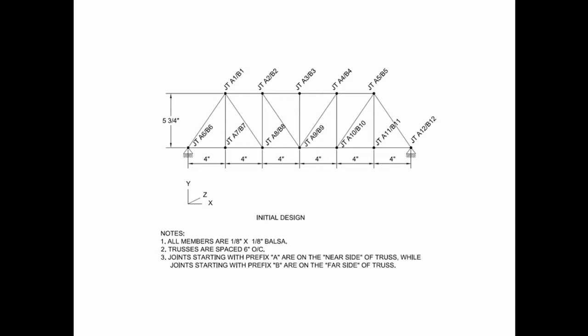For the length of our bridge, we're going to use 24 inches or about 610 millimeters. Our bridge is going to be made up of panels of 4 inches in length. In terms of the width of our bridge, we're going to be using 6 inches. With these dimensions, we should be able to accommodate that through opening of about 125 millimeters wide by 115 millimeters high, which we need all along the length of our bridge.